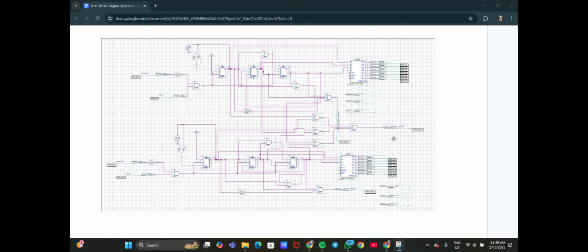For the detector, the circuit uses an XNOR-based detection system to check if both players roll the same number. The Q0, Q1, and Q2 outputs from both counters are combined using XNOR gates to compare the results. If both players get the same value, the detector turns on, indicating that the last player must roll again to break the tie. For the detector, we are using a red LED.